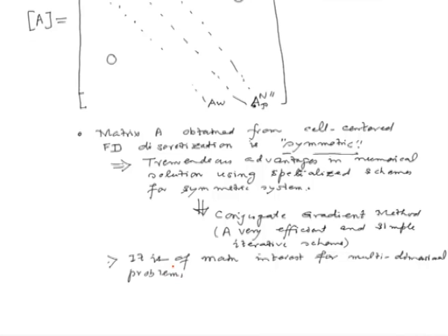Though we showed this matrix to be symmetric starting with a 1D problem, exactly the same structure we would obtain if we had a 2D or 3D problem. If you want, you can verify it yourself, and the procedure for implementation of boundary conditions would remain exactly the same as we have discussed for our simple 1D case.